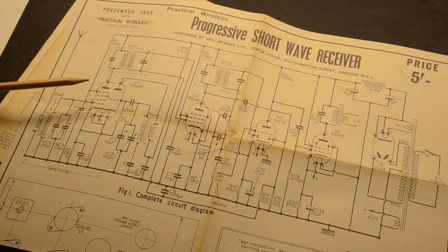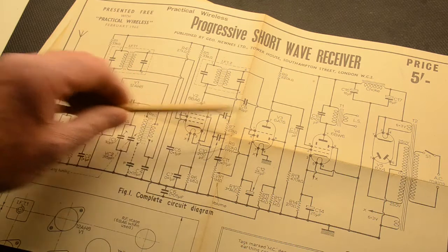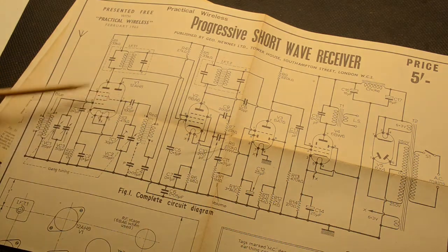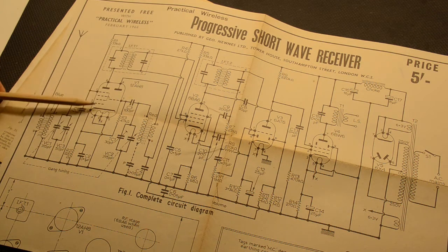Now this is an interesting valve here because unlike this one and these two, there are actually 2 valves in the envelope. What that means is, this is strictly speaking not true. There is actually another grid put in there. There are 5 grids in this half of the valve, call it this end of the valve. On this side there is a triode valve. So you have 2 valves in the same glass envelope.